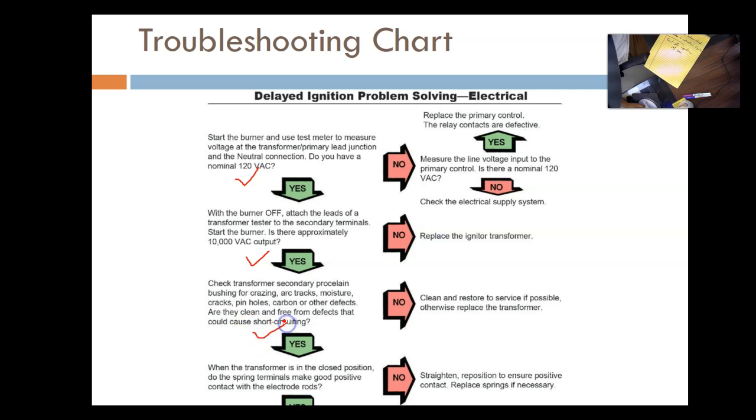You can check for short circuits inside the ceramic holders. Check that in the closed position, the bus bars are touching where they're supposed to. It might be working, but when you close it, it may be touching partially or incompletely.